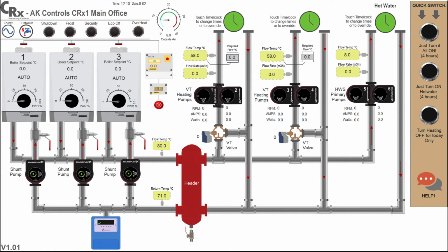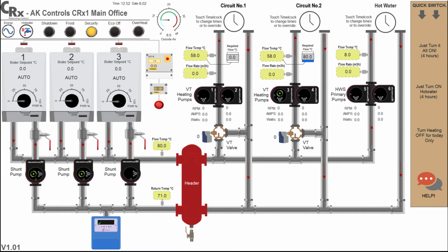It also makes sure the heating and hot water systems are turned off if the building is out of use earlier than expected. The soft off does not affect the heating turning on. CRX will still calculate and turn on the heating at the optimum time to achieve the required space temperature at occupancy. The hot water will also start at the user-defined times. The hot water soft-off feature is reset after midnight, or if a Legionella pasteurization cycle is required.